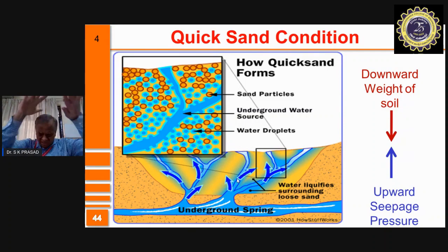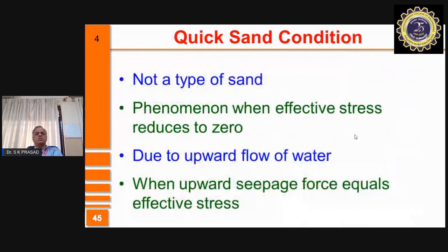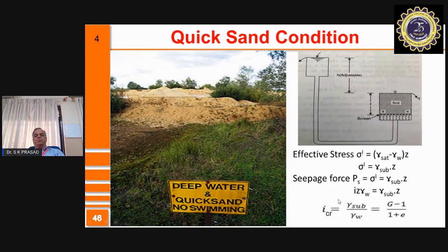It has no strength, no stiffness. You keep your feet on it, your feet will go inside. Even a small weight, even a pen, you keep there, it will not take its load. Soil is behaving like a fluid now. So please note, quicksand condition is not the type of sand. It's a phenomenon when effective stress in the soil reduces to zero. It's because of the upward flow of the seepage water flowing upwards. And when this equals the downward force, the effective stress will become zero.